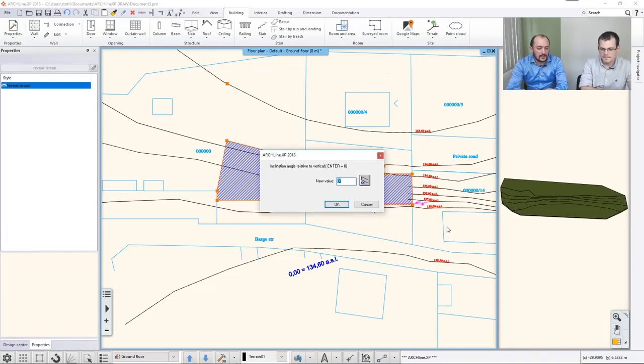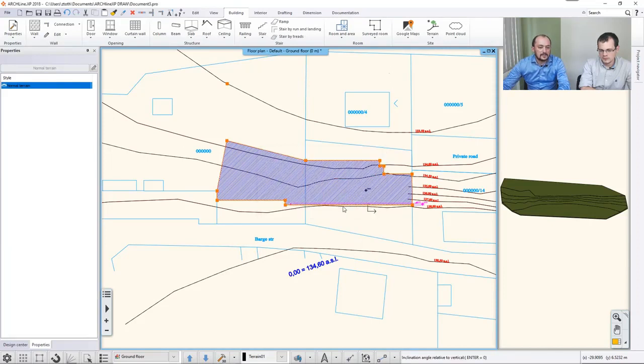For all the sides. Now we are certain that this is not 100% overlapping the terrain, but instead somewhere it will be raised above the terrain and somewhere it will be cut into the terrain. So when I instruct the software to use a 45-degree angle for this cut, then this is what will happen.